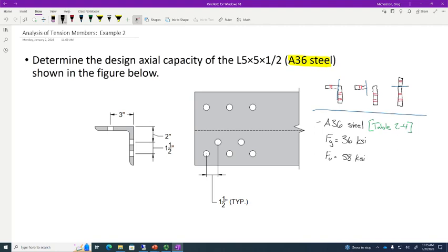Chances are if I go to a service center or go to a mill and I'm looking for W24x76s, unless I ask for something specific, it's going to come in grade A992. That's not to say that W shapes aren't available in other grades. Of course they are. Every one of those gray cells are grades that you can find W shapes in. And there are good reasons for wanting W shapes in different grades.